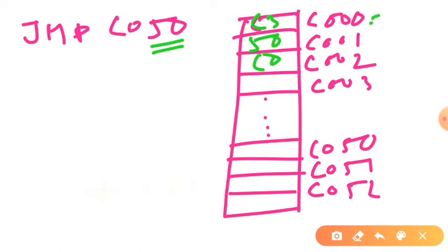Now if we specify the starting memory address C000 to the 8085 microprocessor, it will start execution of this instruction from the memory location C000. It will first fetch this hex code C3 and understand that it is a jump instruction. Then it will read the corresponding target memory address one byte at a time, the lower order byte first, then the higher order byte. In this case it stores the target memory address C050 internally in the WZ register pair.